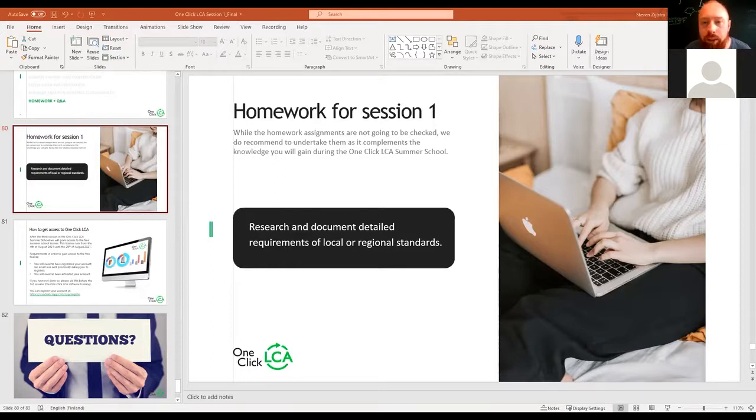Question from Umara: for the decommissioning phase, which countries' regional or environmental disposal and recycling practices are being adopted? When we look at decommissioning, so end-of-life emissions, we basically look at the material subtype. If you have a CLT element, it usually follows very certain end-of-life processes. If you have concrete, it might be recycled, or it might be downgraded to aggregate, depending on whether it's precast or ready-mix. So we don't necessarily take a look at countries or regional things. We look at the most common end-of-life processes and give you those as options.